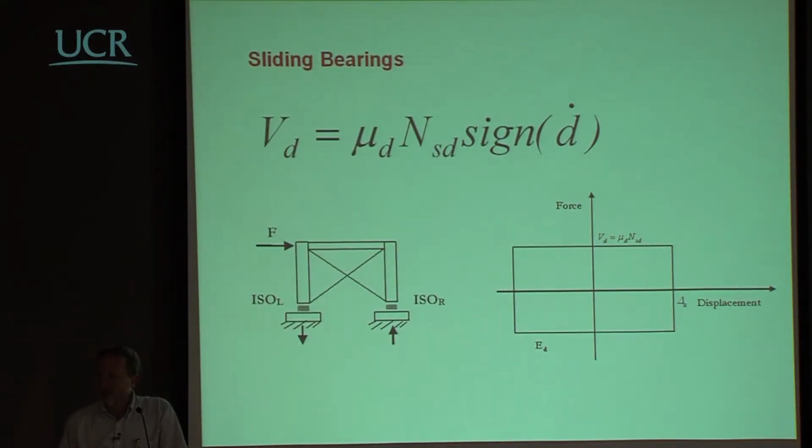So it's an extremely large value, but unfortunately there is no recentering capacity, there is no control of the response, and what is possibly more important is that you will not be behaving going along this or something like that, but it is like, you may remember, the famous sliding block of Newmark. So the structure will respond without any movement for a large variation of acceleration, and then it will move only in the cycles that exceed that value, that will activate the friction between the two of them.